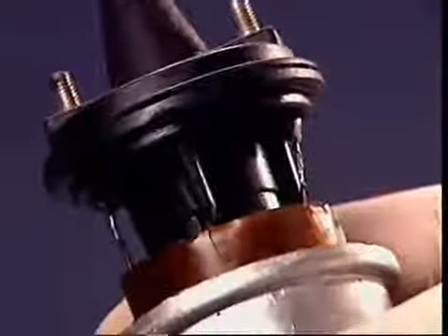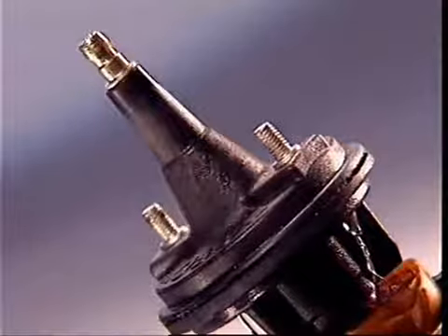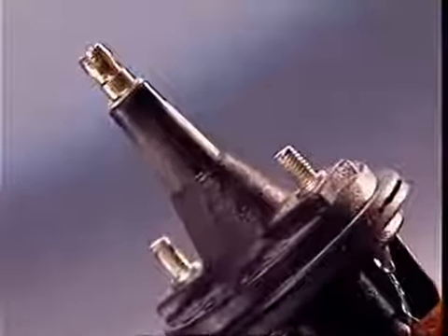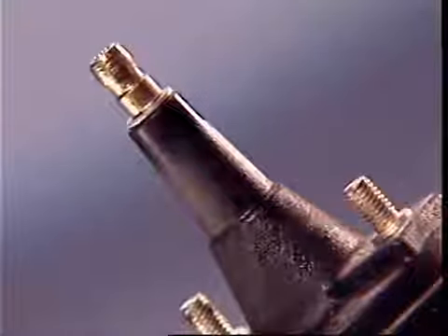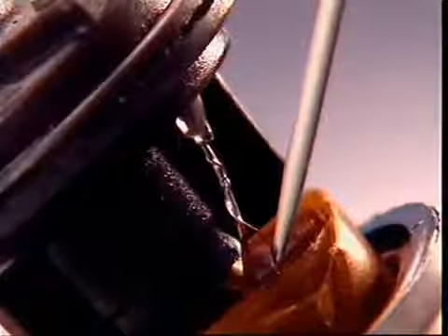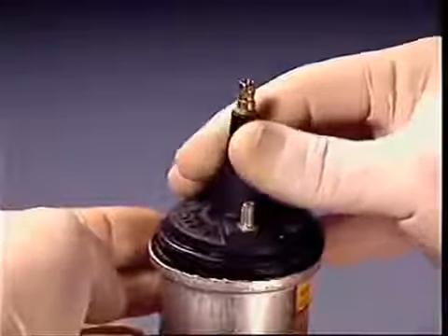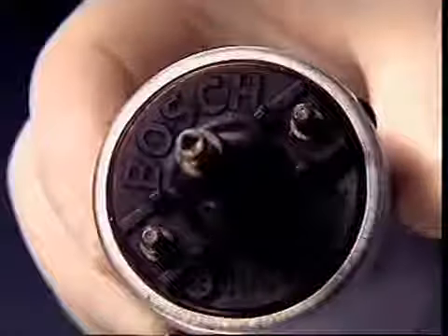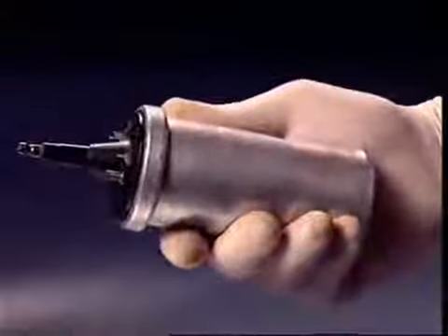The ends of the primary winding are connected internally to each. Provision is also made externally for a heavy insulated center terminal to connect the high-tension coil lead to the distributor cap. One end of the secondary winding is connected to this center terminal, and the other end is connected to one end of the primary winding. A rubber seal and a molded insulated cap seal the assembly in the container, and the container edges are swaged over to bind the coil into a compact, vibration-free unit.